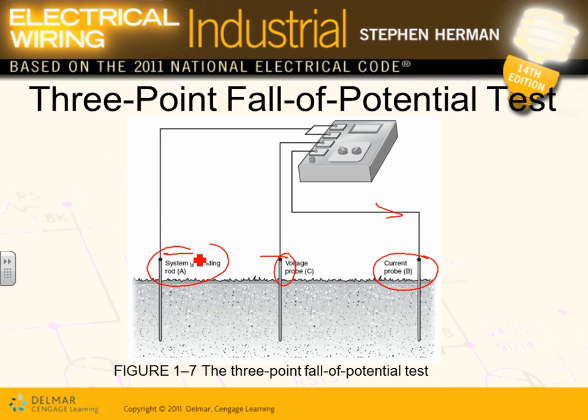Shoot the current, measure the voltage, calculate the resistance. When you have multiple values, what do you do to get the real value or close to the real value? Average them. So they average them, guys, and they tell you, oh, your site is 4.5 ohm, or 5 ohm, or 25 ohm.